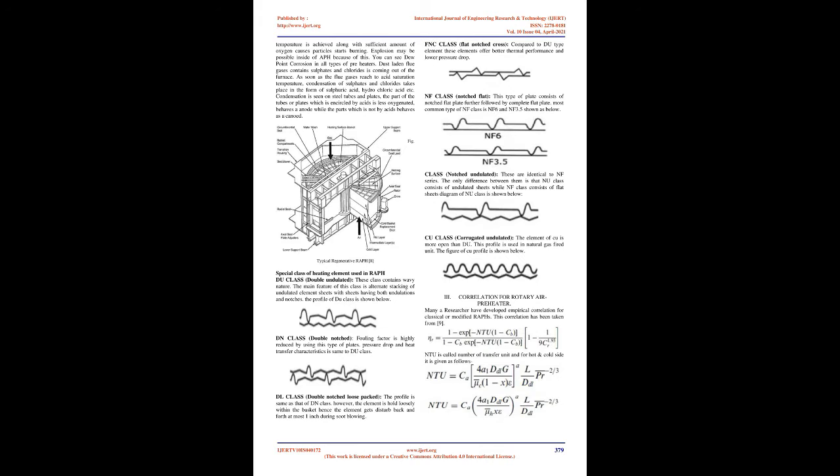The various modifications of the design of the rotary air preheater are widely used in modern power plants for fast heat transfer for boiler and condenser. RAPH performs better operation after modification in the matrix shell for a high rate of heat transfer. However, the pressure drop in the rotary air preheater in the matrix shell is higher, for a higher loss consideration. So an optimal design is needed to achieve the maximum heat transfer performance with minimum heat loss and leakage air/pressure.